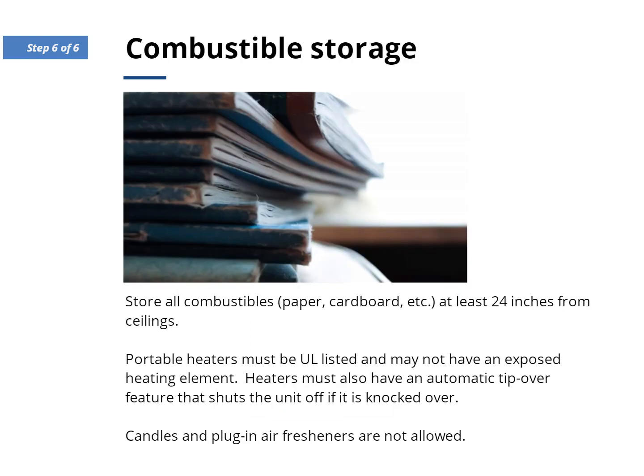Combustible storage. All combustible materials such as paper and cardboard must be stored at least 24 inches from ceilings. Portable heaters must be UL listed and may not have an exposed heating element. Heaters must have an automatic tip-over feature that shuts the unit off if it is knocked over. Candles and plug-in air fresheners are not allowed.